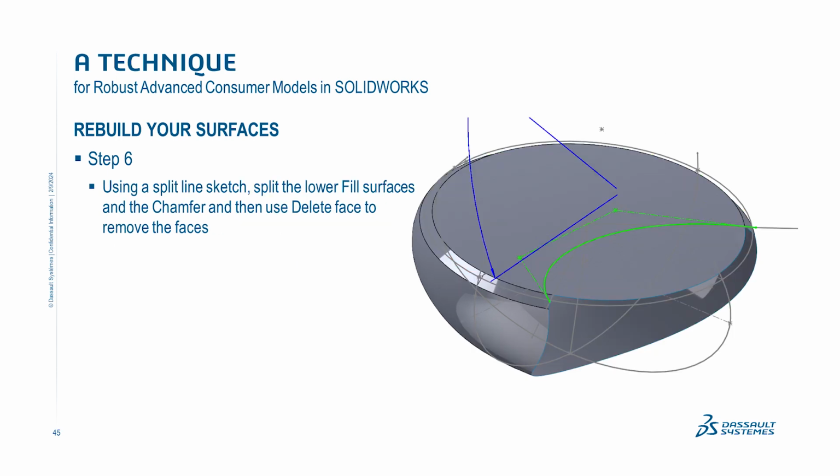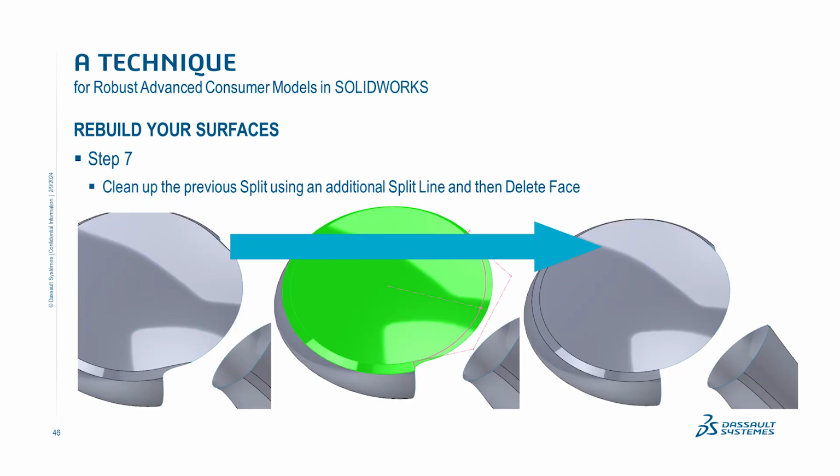At this point, I know that I have to trim away part of this forward area because I have to do my transition between this forward interface area of the controller and the handle. So I'm using a 2D sketch to trim away part of that surface that I created. And then I do a further trim to get the remaining material to be at the chamfer, perpendicular to that top elliptical face.